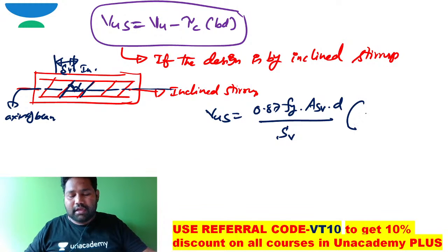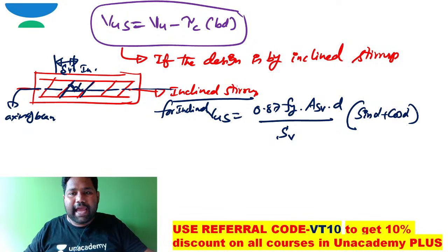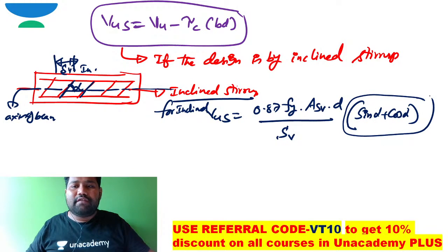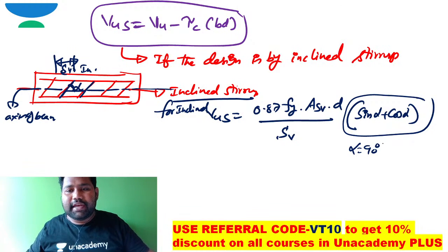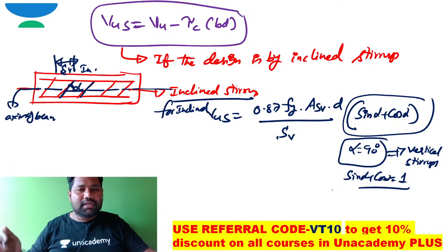So the extra element that will come into the equation for inclined stirrups is sine alpha plus cos alpha. This term is only for inclined stirrups, because for vertical stirrups, alpha is equal to 90 degrees. Then sine alpha plus cos alpha is equal to 1 in that particular case. So this is how we can work it out.